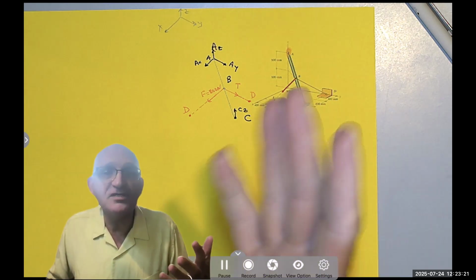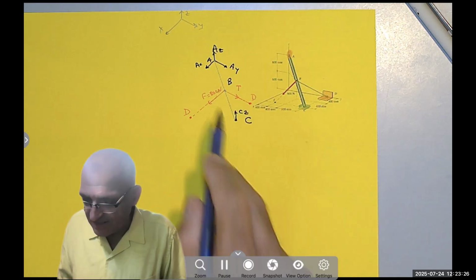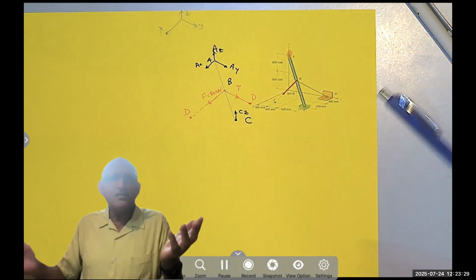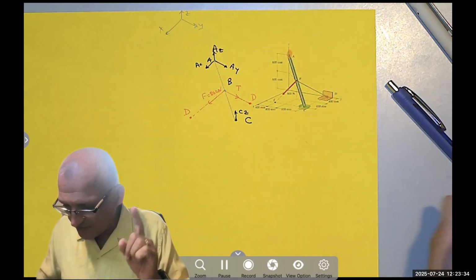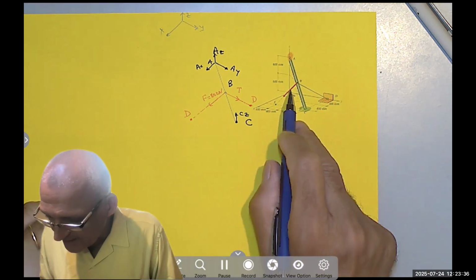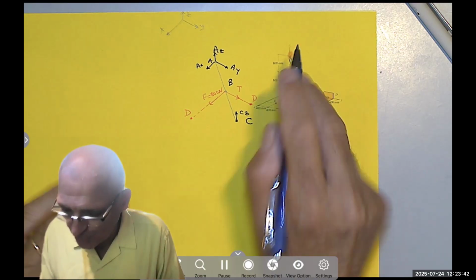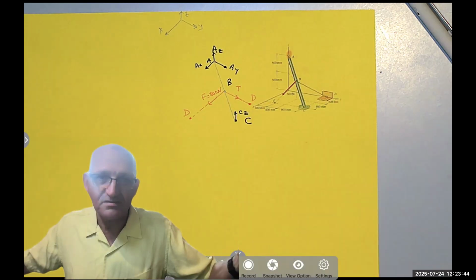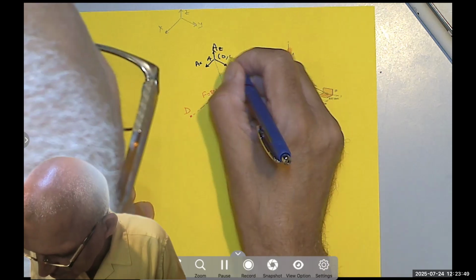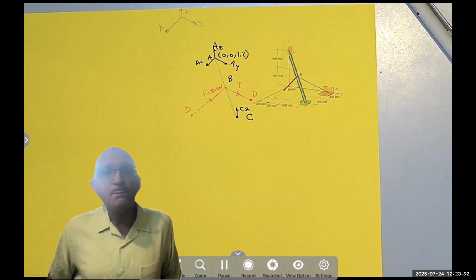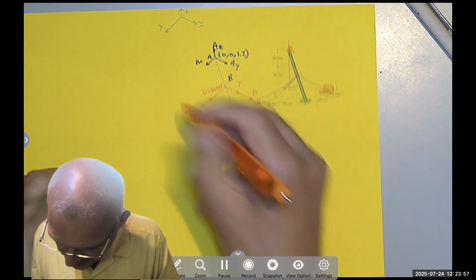Because I don't know the dimensions. How can I express F or these? These are easy, but how do I express F and T in vector form, right? I can't. So please don't forget, point A is 0, 0, 1200 millimeter or 1.2 meter. Let's work with meters because we don't need all these zeros. So I'm going to say 0, 0, 1.2. Notice I have 5 points. Oops, I wrote D instead of E.